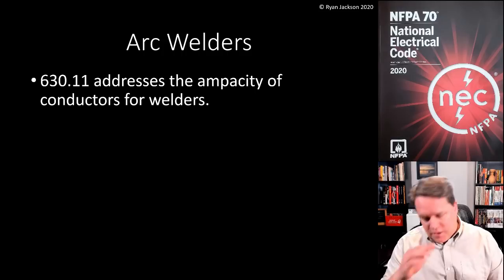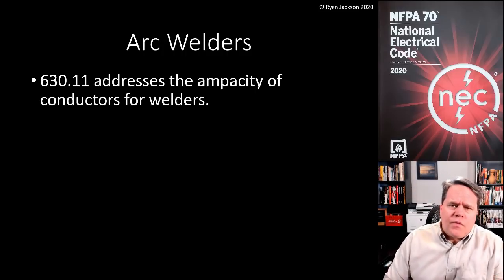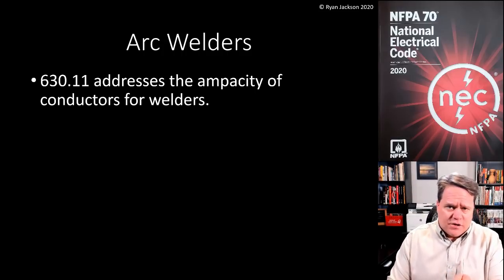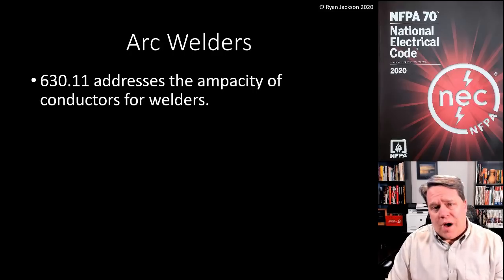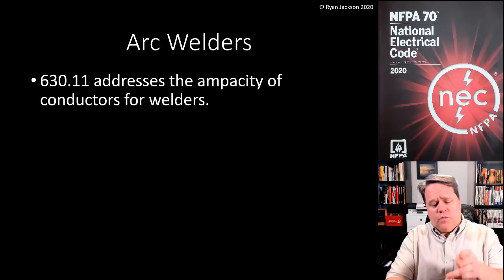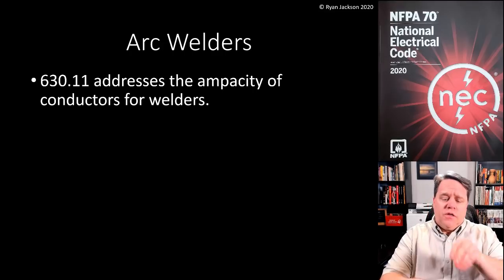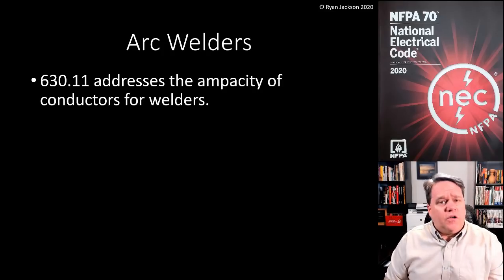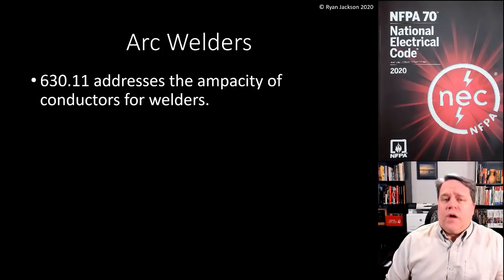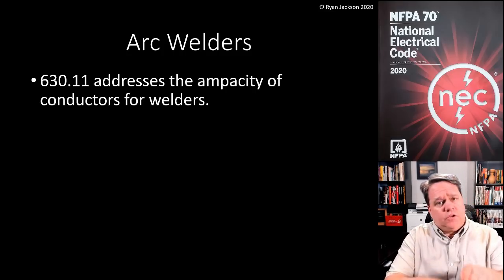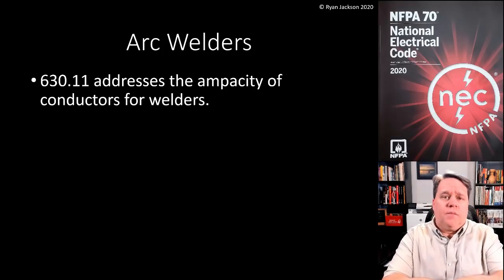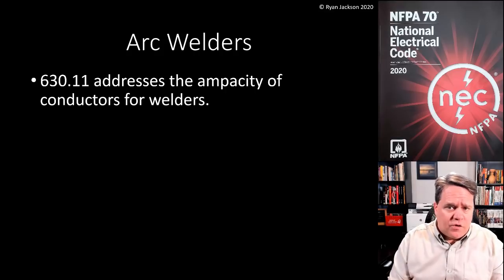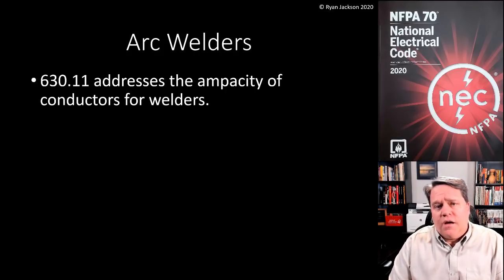But my understanding of arc welding is that it has an electrode, like a welding rod or wire. We have the two items, and then we have a third item, an electrode, that we melt and join the two materials together. Whereas with resistance welding, we don't have that third item. We just have the two items that we're going to weld together. We heat them up and we weld them together. So that's kind of the difference between arc welding and resistance welding.